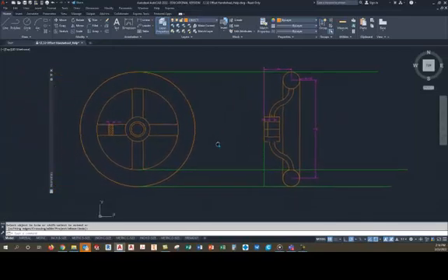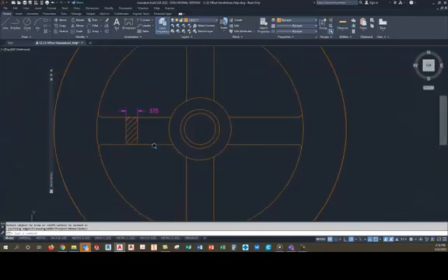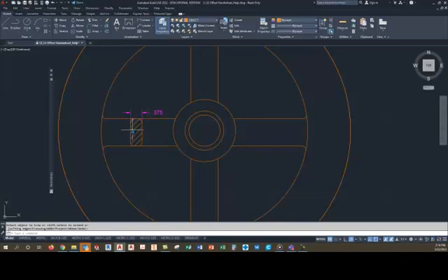Now the other thing on the answer sheet that I think I still have on the class is it shows a cross section of this, but if you look at your drawing that you're given, it actually looks like an ellipse. So we need to have some dimensions here, and one way you can do that, besides needing a center line right here on this, you could do a broken section here. If you did a broken out section right here with the revolved section as well, then you could probably get away with putting the other dimension right here.